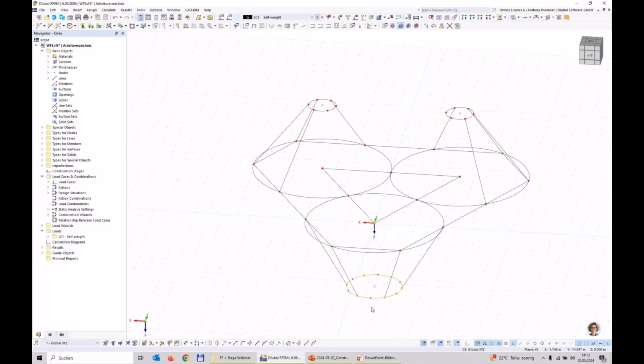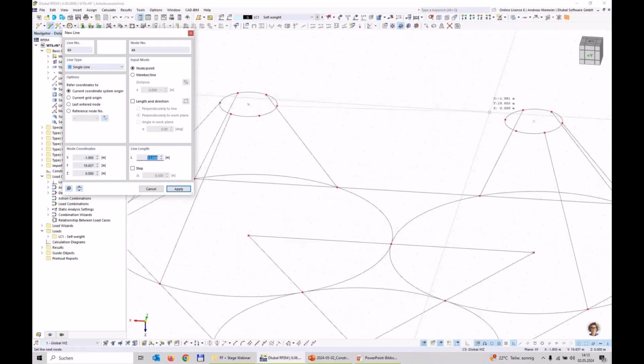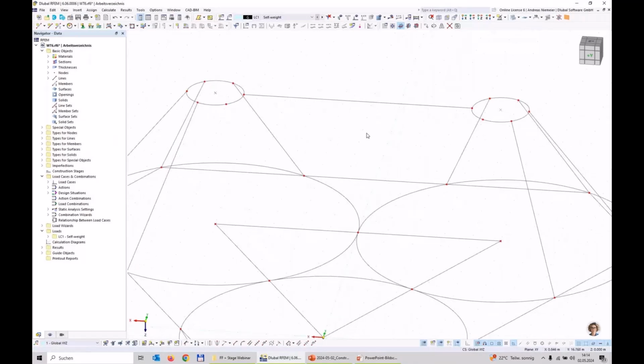So now you can ask, of course, why I'm drawing this so stupidly with these rough lines. This is my target. I try to simulate this structure in a really rough way to define only the boundaries. My main target is to create a model that could be meshed and that looks roughly like what I want to do, because the real optimal shape will be found by a computer process.